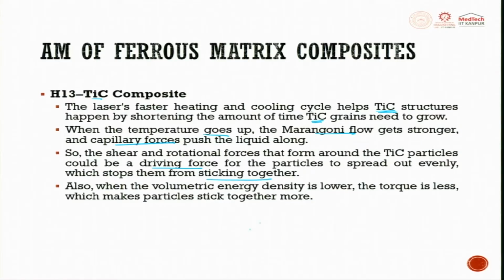So, there will be a shearing and a rotational force that forms around the TiC. TiC particle is here, this is TiC, and then there will be a shear and a driving rotational force, which could be a driving force for the particles to spread out evenly, which stops them from sticking together. So, this motion of Marangoni force and capillary action tries to disperse TiC particles nicely in the H13 matrix.